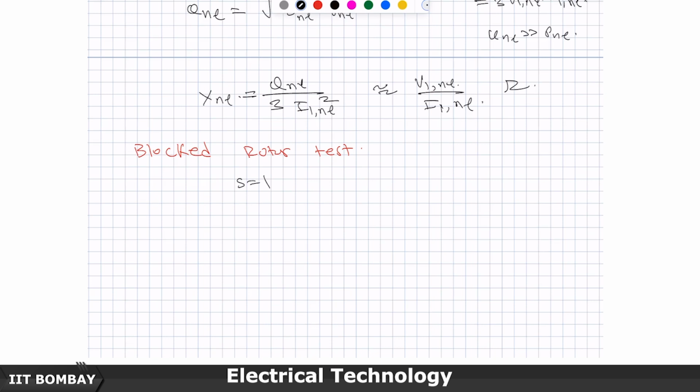Now, there are two small points that I want to mention here. First, leakage inductances in an induction motor are dependent upon operating condition because of the saturation effect.